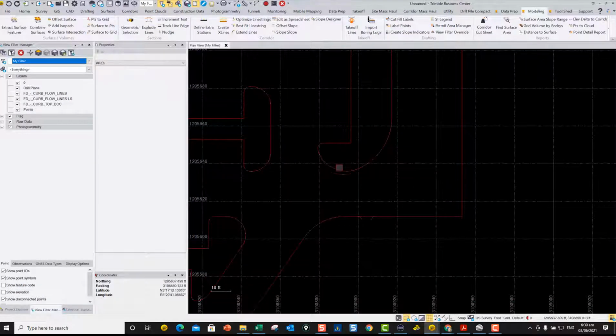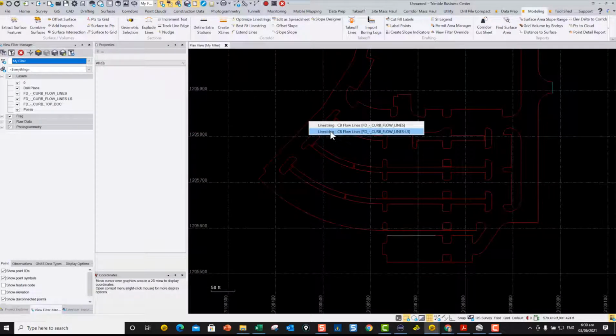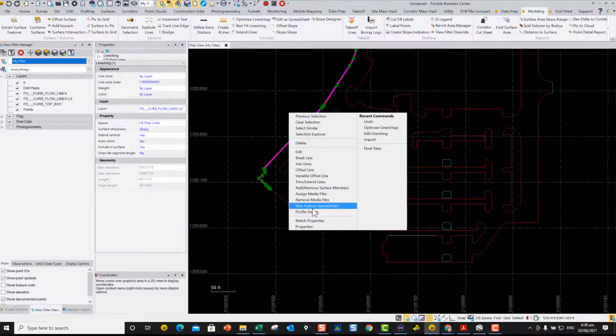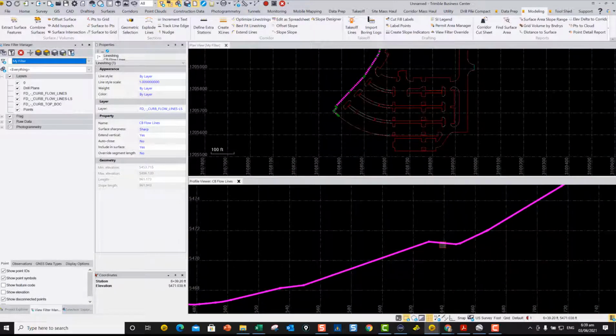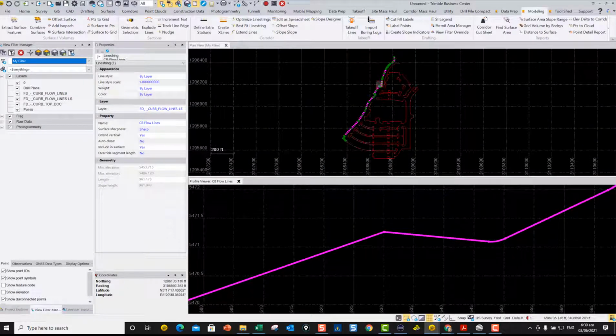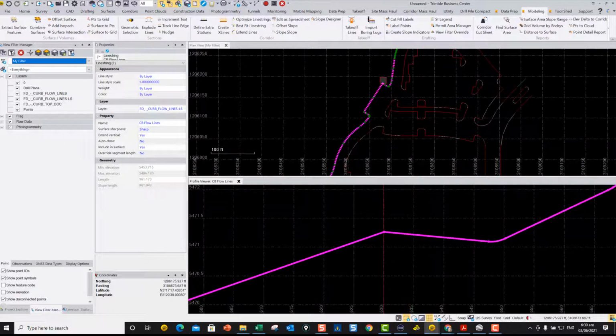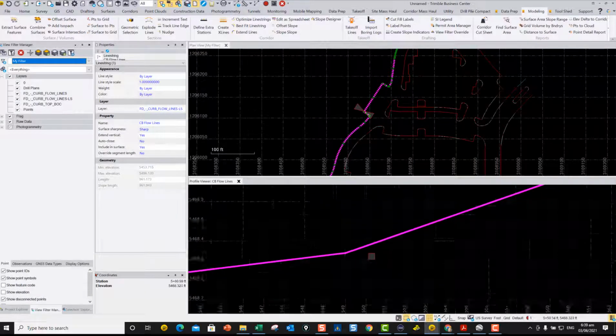And if we look at the vertical, if I go back to this one that we looked at earlier, for instance here, and take a look at the vertical profile of that, what we're going to see here now is, if I stretch the vertical up, well, we've still got the angle break at that right angle corner right here, where it came into the corner here. You can see that's that point right here, where we told it we didn't want to, but at this corner, it's actually fitted the vertical curvature through here, and you'll see the same thing apply.